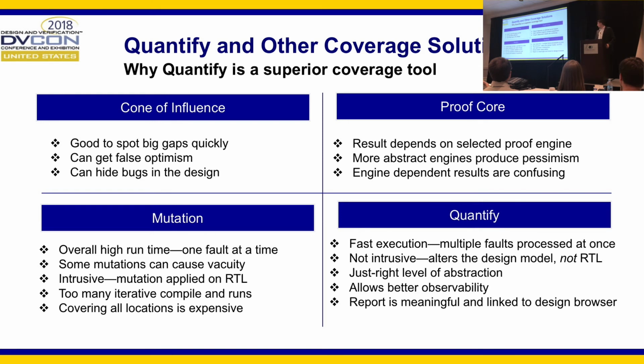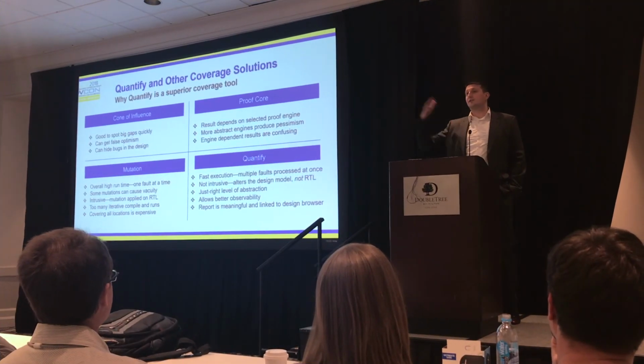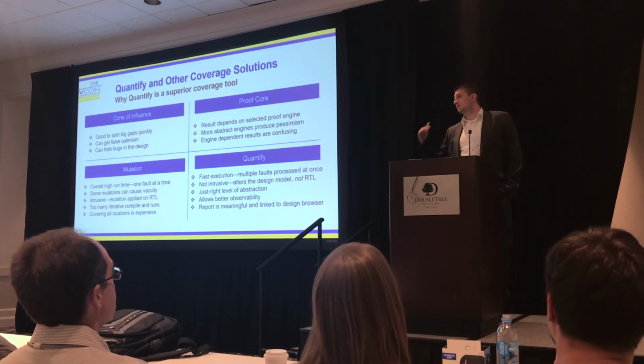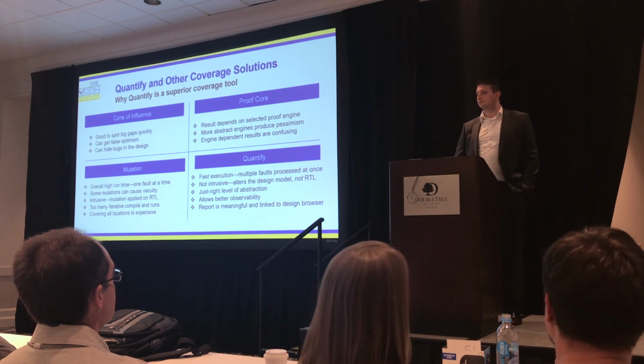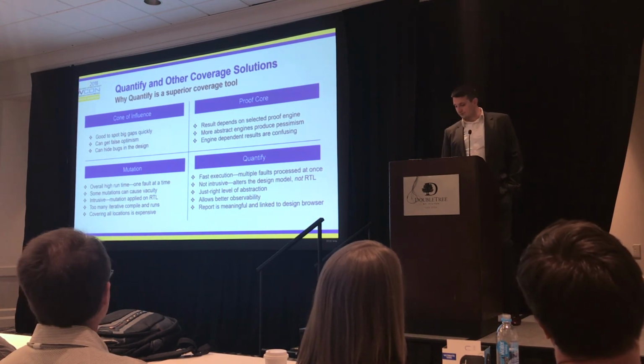And then in the end we have what we talked about, Quantify with fast execution, so we can actually process multiple faults at once. And it's non-intrusive, it's done on the model, not the RTL. It's what we call a just-right level of abstraction, and we focus on the actual observability of your checkers. And as you have seen, the HTML report can be meaningful and can be tailored to different uses, whether it's design, management, or verification engineer. They all share the same view.